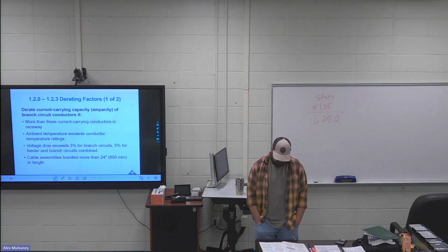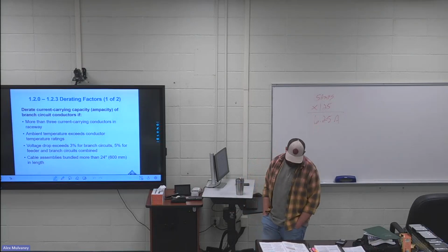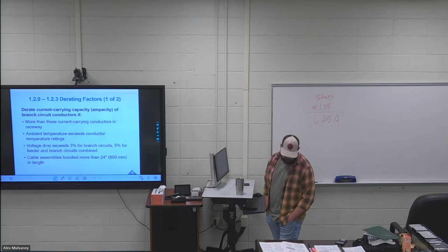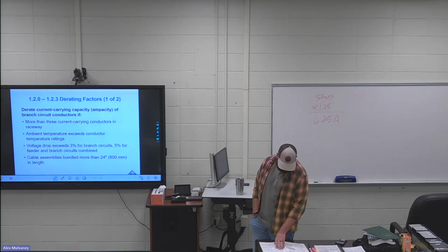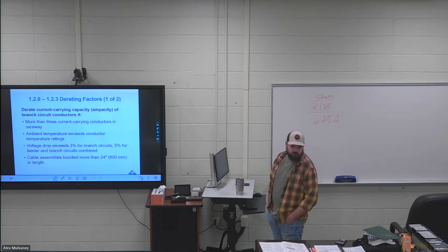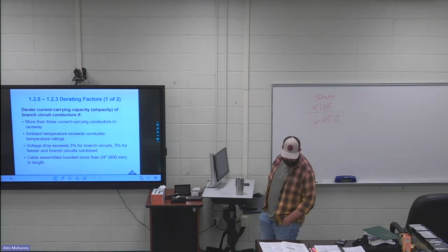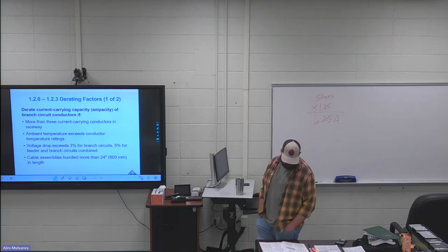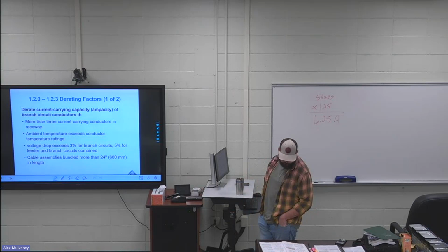First thing you want to do is determine the length center of the circuit by first multiplying the outlet loads by their distance from the circuit source. So outlet 1, if we look up at the top, the first one is 30 amps at 60 feet. Outlet 1 is 60 feet times 30 amps equals 1,800. Outlet 2 is 80 feet times 30 amps, which is 2,400.